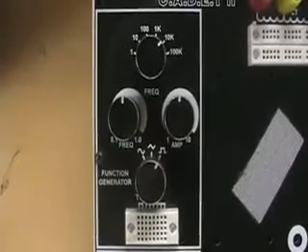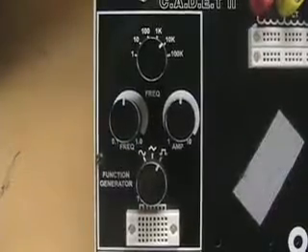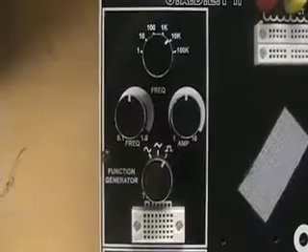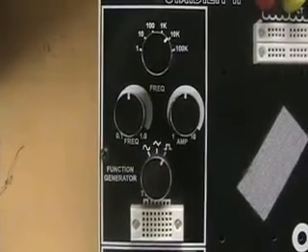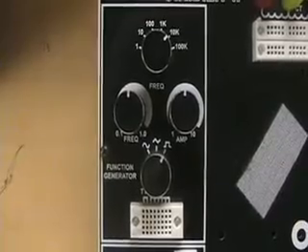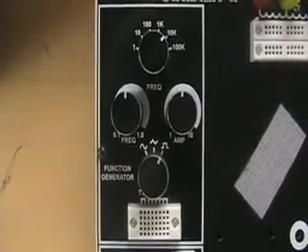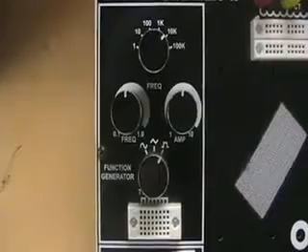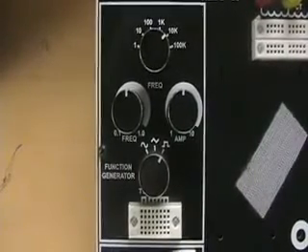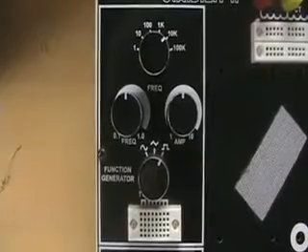In the top left corner, we find the function generator. It is useful for providing your circuit with a clock signal. In configuring the wave, you should first choose which waveform you would like to use. The CADET II board provides sine, triangle, square, and TTL waveforms. For your digital circuit, the TTL waveform is the most appropriate because it is a square wave with a minimum of 0 volts and a maximum of 5 volts.